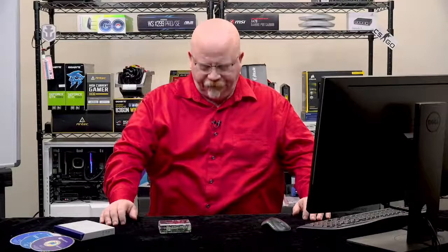That wire can be in one of 2 states. It can be either off or on, right? So what we could say is that with a 1-bit address bus, we could address up to 2 different bytes of RAM. We could have 2 separate commands. And if it was off, it would grab the top one, and if it was on, we'd grab the second one. So that wouldn't be very useful if we only had 2 bytes of RAM in a computer, so we probably need a few more wires, right? Well, let's add a few more and watch what happens.